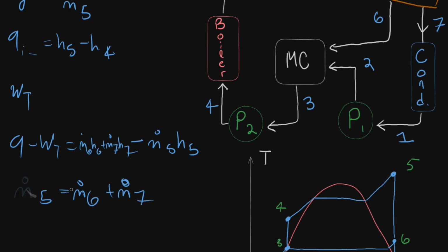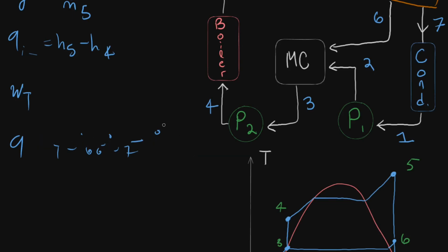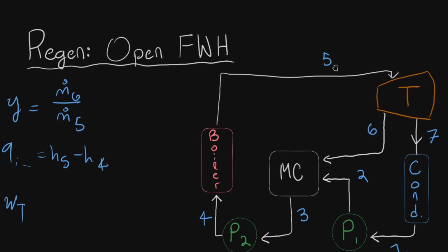Anyway, you could work backwards from that, or you can just think about intuitively what's going to happen. I think that's a little bit easier to understand, and it's also a little bit faster because you don't have to work through this every time. So basically, all of the mass in the turbine is at least going to go from state 5 to state 6, right? Which means that we have H5 minus H6 per amount of mass flowing through the boiler. I should be more specific here. We're talking about the work output from the turbine per unit mass flowing through the boiler.